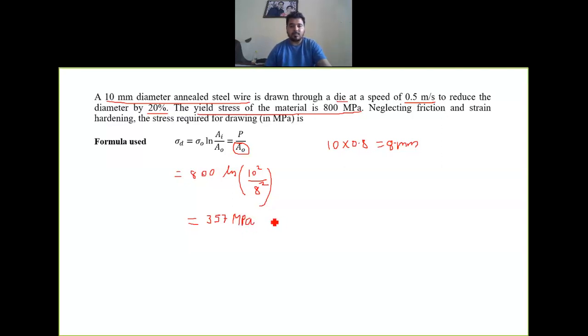This is a linked question with the next question. So we continue with the numerical here. We can calculate the force with the help of drawing stress. In wire drawing operation, force is equal to sigma d into outer area.